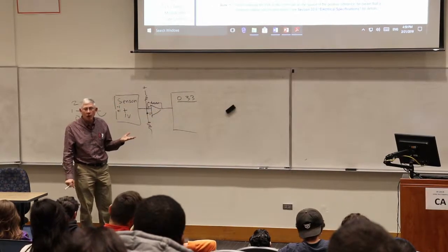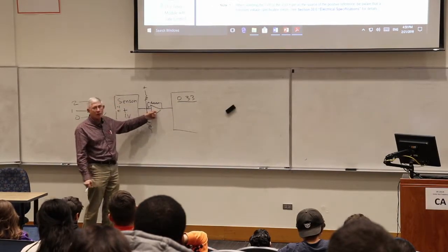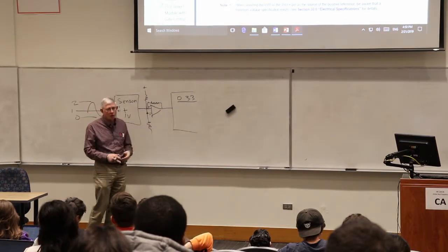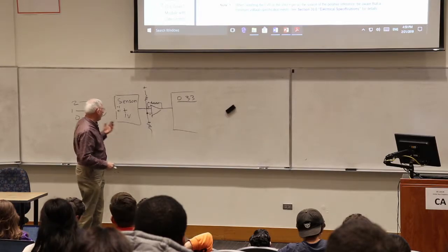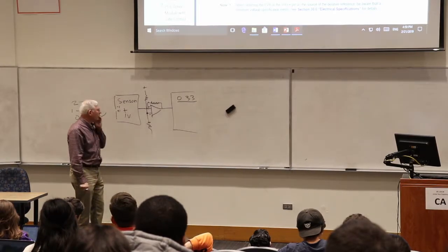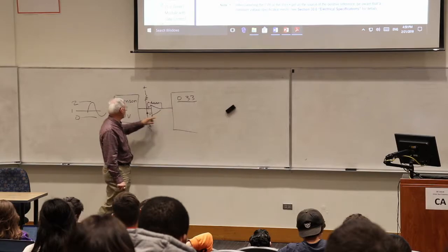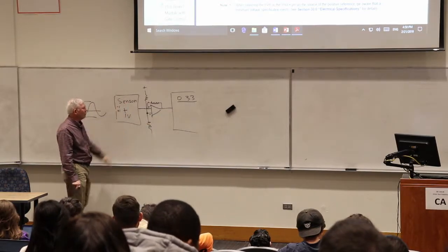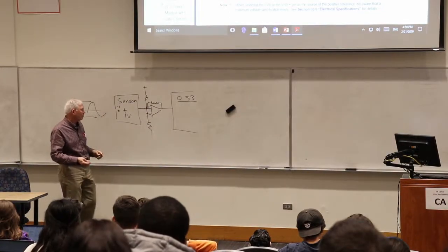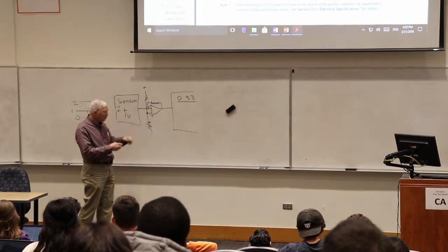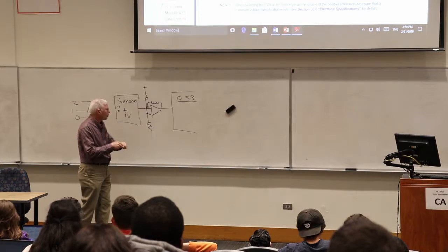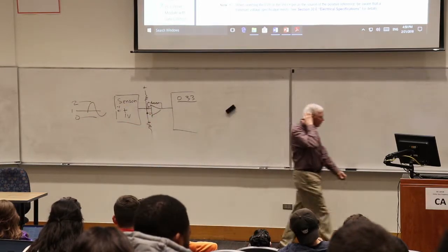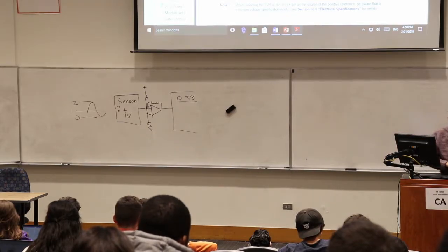Now, some of the microprocessors in this family have built-in op amps inside the die, so you can just use those. But in many cases, you'd still have a problem, because even inside the die, they're restricted to the 5 volts. And they can't take the negative signal. So sometimes that doesn't really help you. Usually you have to. So make sure when you're doing your analog coursework that you do learn how to use op amps, because they're very critical in interfacing analog signals to our A to D converters.